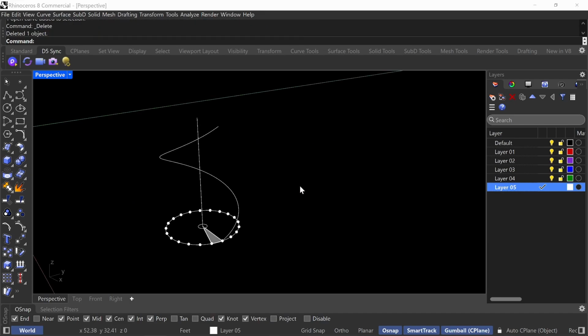So what we want to do is make sure that we understand the riser height. In our design criteria, we did 12 feet times 12, which is 144, to convert it to inches. We divided it by 7, and that gave us the number of risers you need, which was like 20 point something. So we rounded up to 21. That means the actual riser height is going to be less than that.